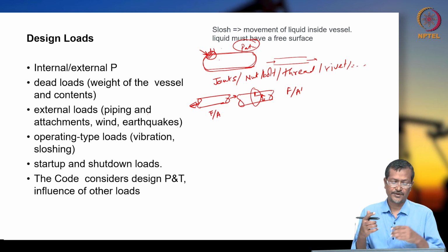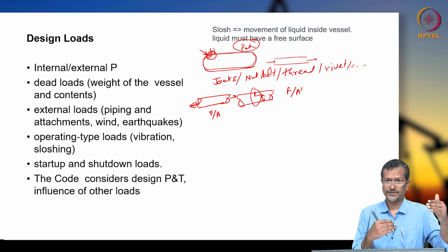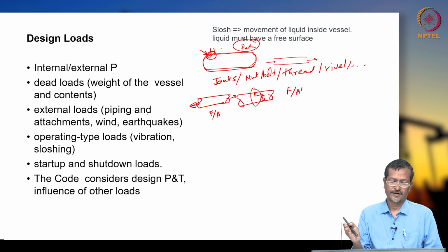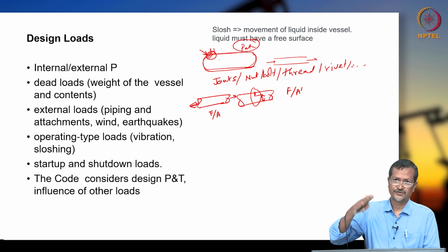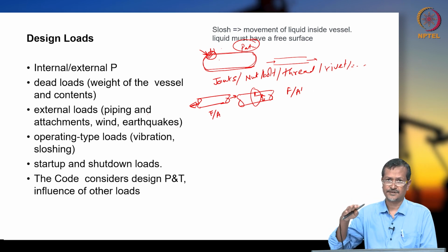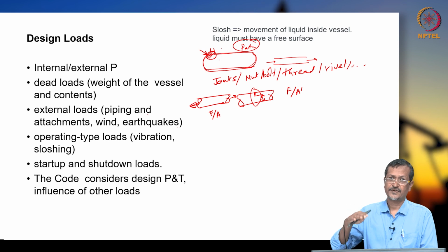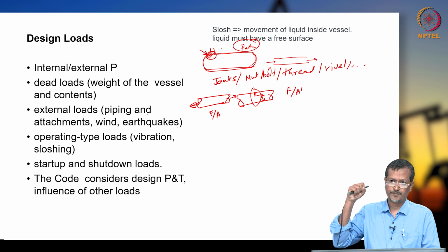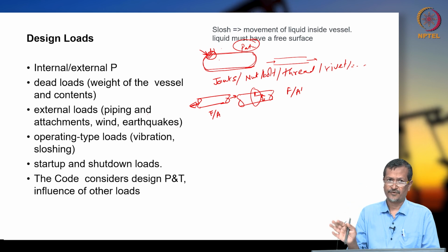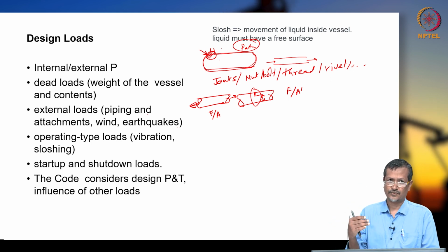One is fluid property, then internal pressure, external pressure, and other factors like whether it is dead load or dynamic load. Dynamic load means pressure is fluctuating very much because of certain reasons. Fluctuating pressure means dynamic load. But if you have one vessel and you just pump high pressure fluid and then forget it, there is no pressure change, so there will be static loading, right?